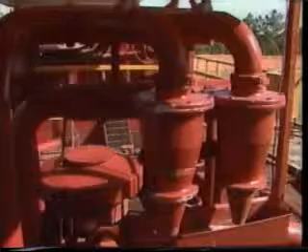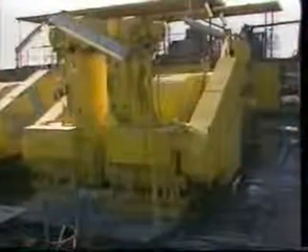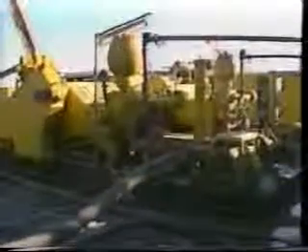Returning through the blowout preventers and mud return line, the mixture falls across the shale shaker, where the majority of the drilled particles are screened out and discarded. The mud then flows into the settling pit, then returns to the suction pit to begin the circuit again. While in the settling pit, the mud may be processed through various devices to remove finer sizes of drilled solids. The mud pumps which drive this system are driven by electricity or mechanical linkage powered by diesel engines.